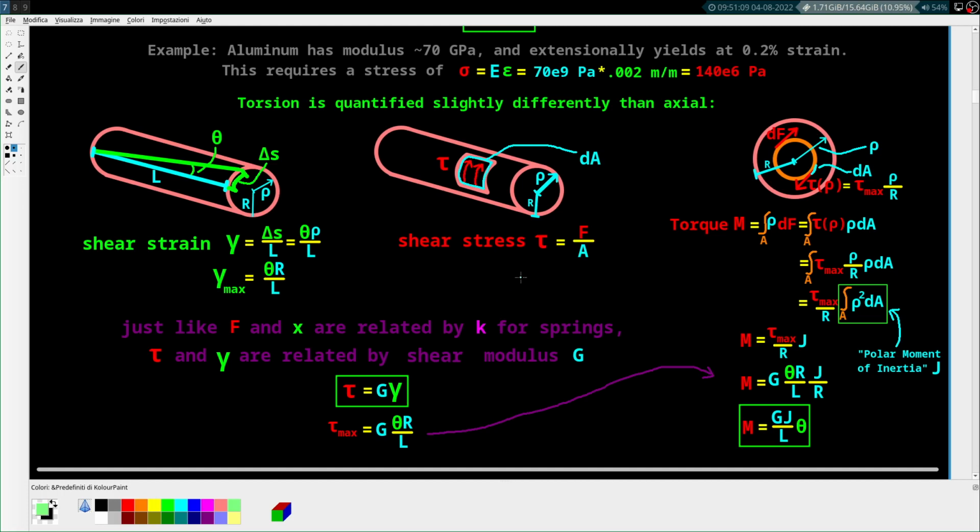And the thing is, you can actually plug in numbers here and do a moment equilibrium. I'll do that right now just to explain this. So basically, if you apply a torque on this member about its central axis, you can take this, basically, what are the internal forces, internal stresses? They have to be equal to each other, and they have to also equal the applied moment. And so you kind of look at this sort of free body diagram here.